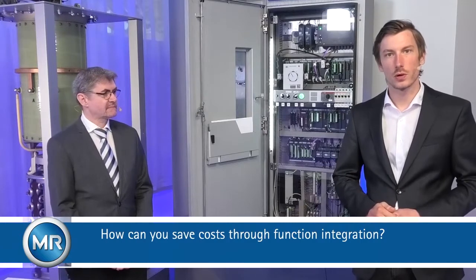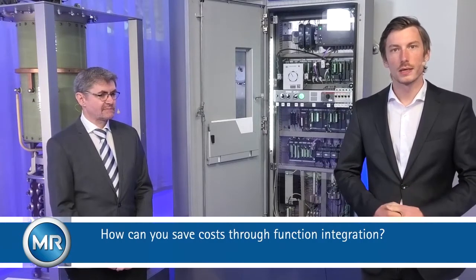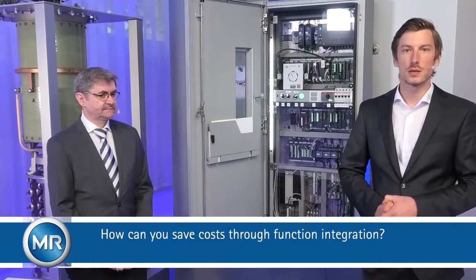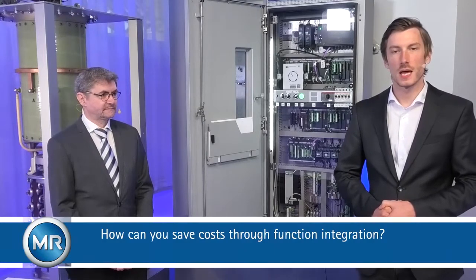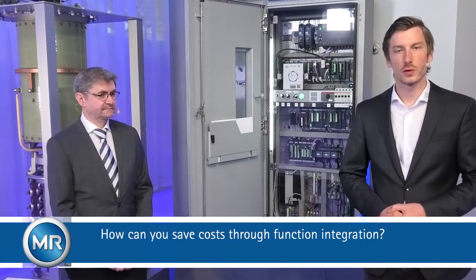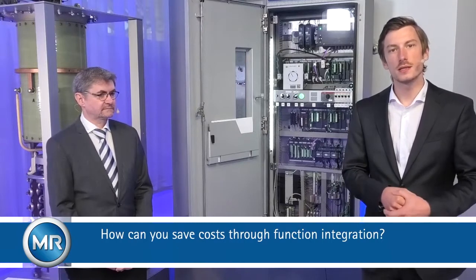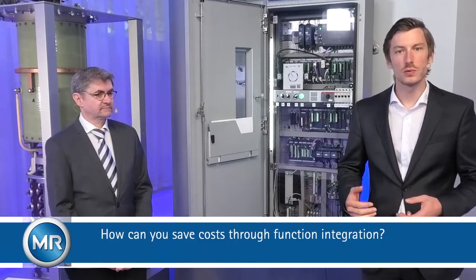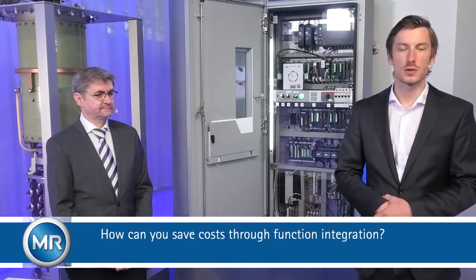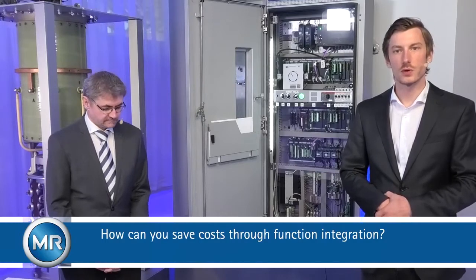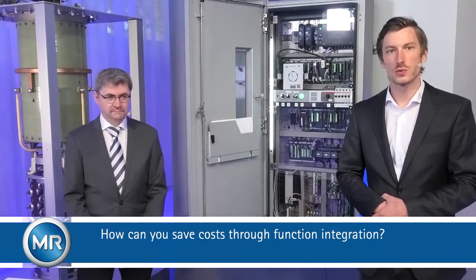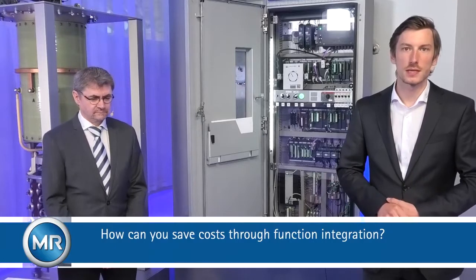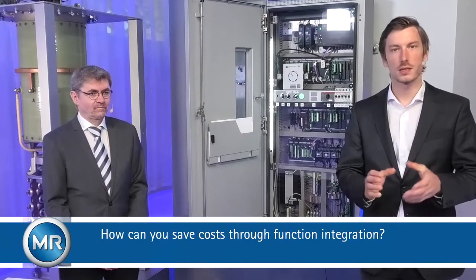So for example, for the thermal measurements and the thermal calculations, you need the load of the transformer. And you also need the load of the transformer for the voltage regulator. So you just need to measure the load once. And you also need just one CPU for all the different applications on the transformer. So that's why it's sufficient to have the input-output modules, to have a CPU, and wire all the sensors that you need for the application to one single interface.